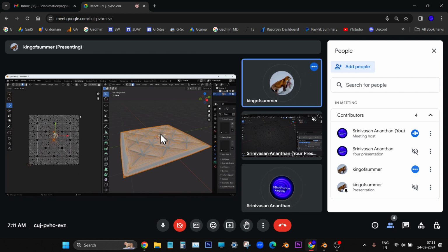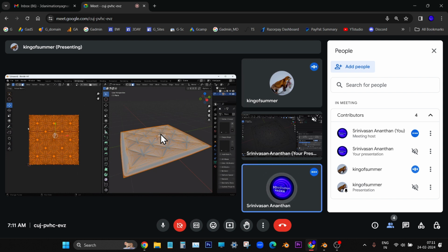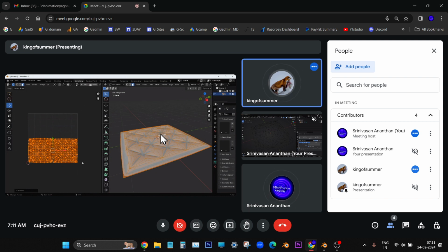Right now, you can switch on the sync button. Now press U to unwrap, because we have done the mark seam. Now it has split into two, because of the seam we marked, the cut where it should be cut, that we defined to Blender. It is like drawing a line with a chalk piece and making the cut.